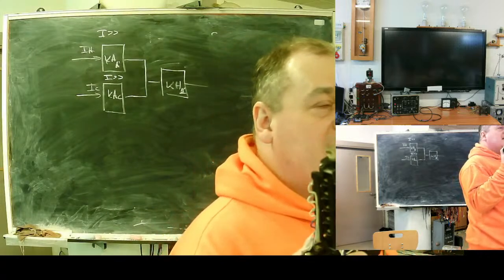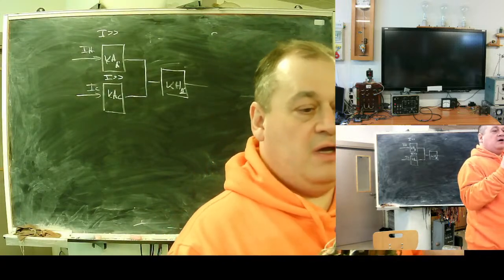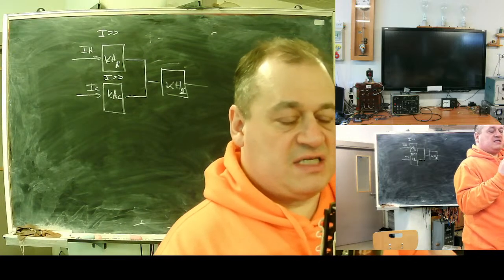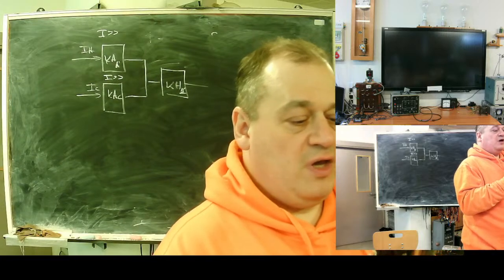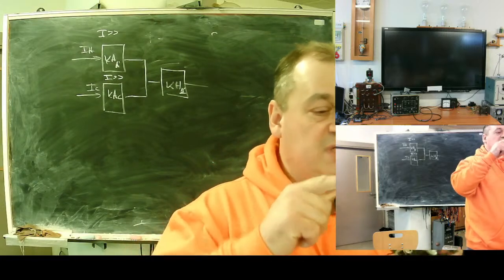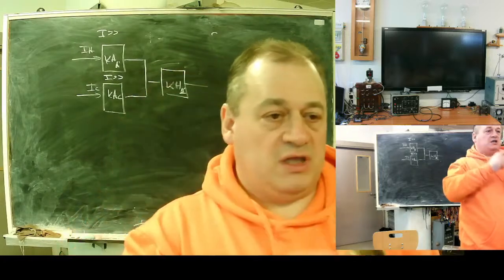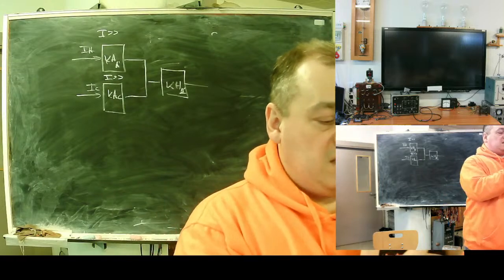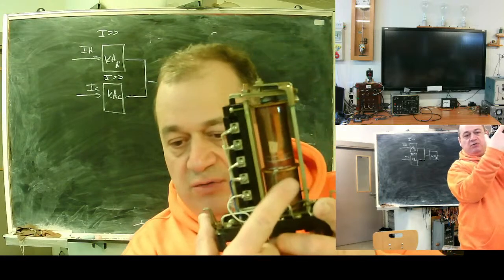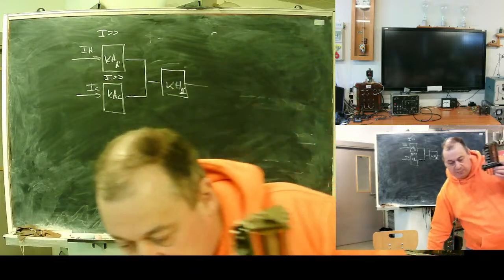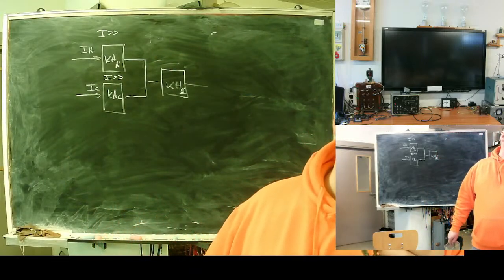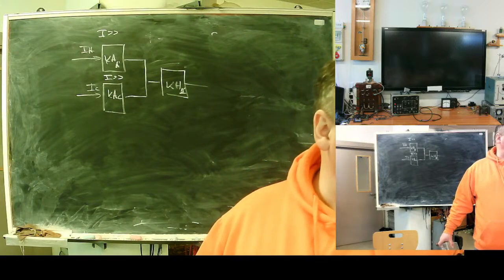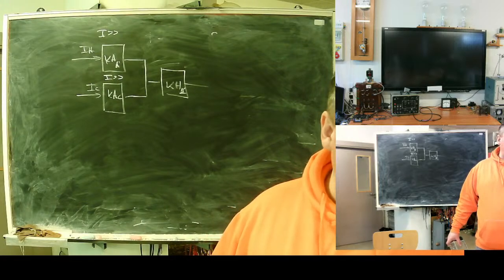It's a delayed return relay. It has a coil like simple relays, and this copper cylinder. If you activate it, it closes these contacts. But when you remove voltage, current in this cylinder will keep it on for maybe a second, maybe a bit longer. It's a special delayed deactivation relay.